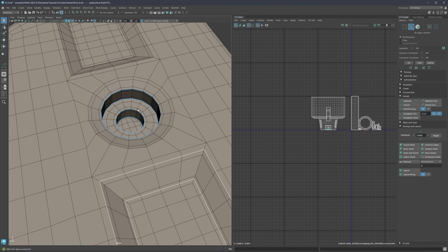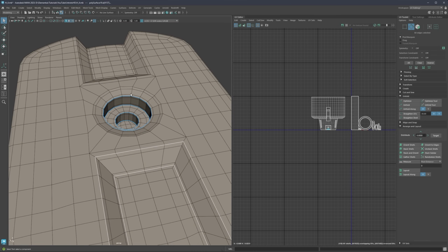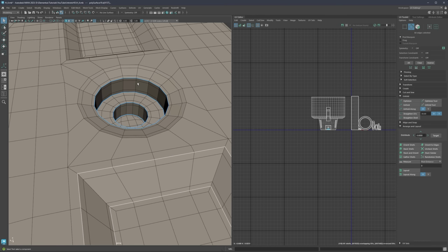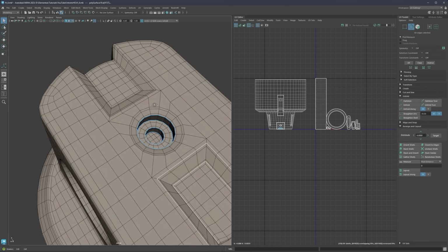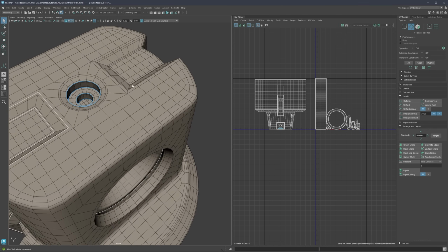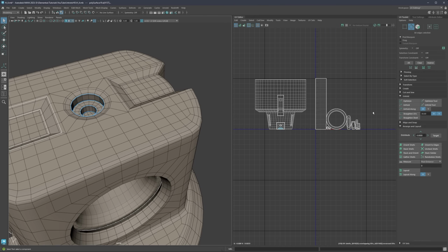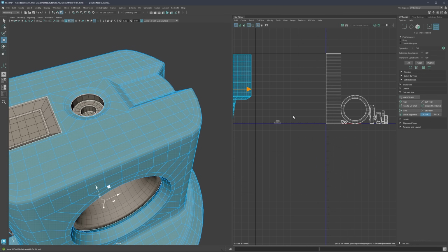For now, just for the sake of practice, we're gonna create cuts everywhere there is depth, but later, when you're more comfortable with all of this, you will also notice that some parts you can skip and something will still unfold nicely. So just again, for the sake of practice, we're also going to look for that difference in depth. So again, let's create a cut. Cut, right click, UV shell, move tool, move this to the side.